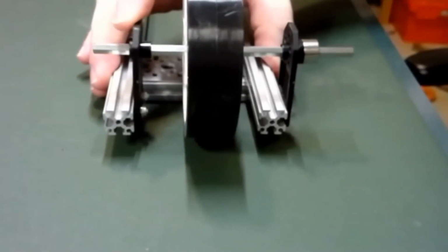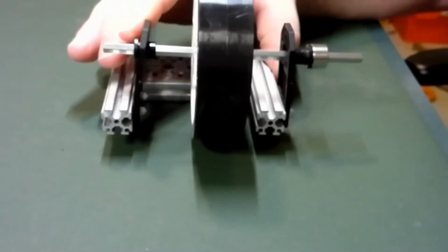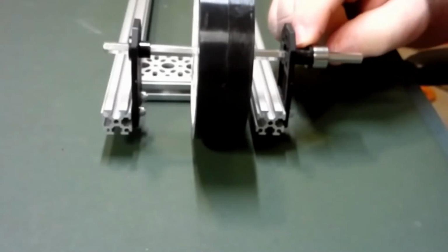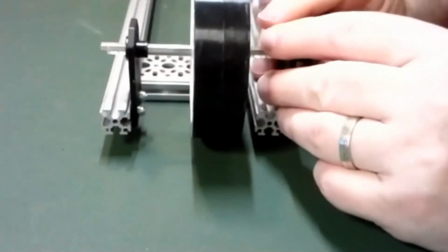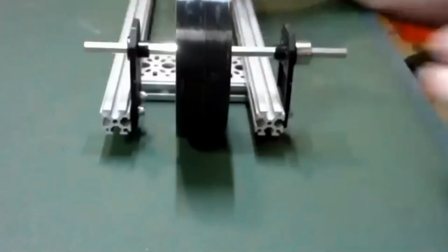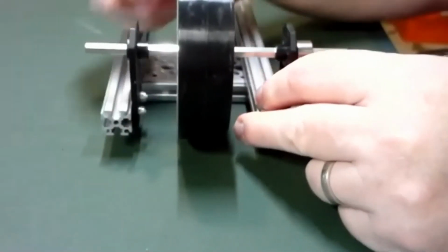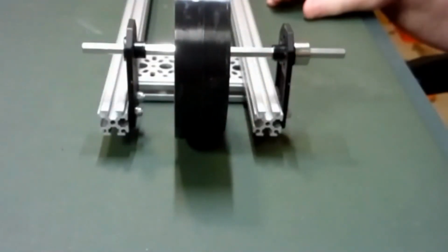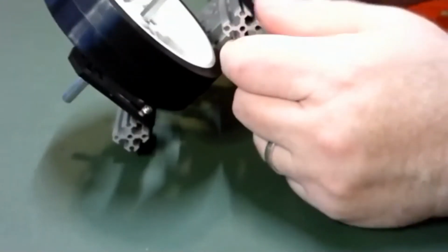I can even bend them so much that the bushing, the bearing, comes out of its socket, just by virtue of bending the brackets. So if you're using plastic brackets or pieces, you have to be careful that they're able to bend. You could go to metal brackets, but REV doesn't sell metal brackets that would be deep enough for me to get my axle far enough away to put a Mecanum wheel in here.